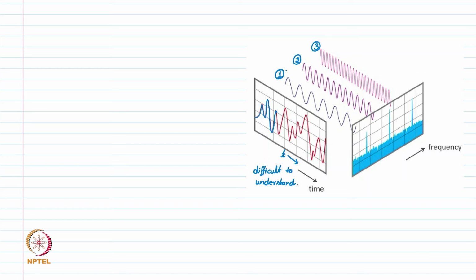So, what we do, we take the FFT, which is going to split this signal into its frequency components 1, 2, 3, and now in the frequency domain the x-axis is the frequency axis. This is frequency 1. In the frequency domain, it is just a single frequency. For example, this is 1 kilohertz, this is 2 kilohertz, and this may be, let us say, 5 kilohertz. So, in the frequency domain, each is only a single point, and the magnitude is the amplitude of this signal here.